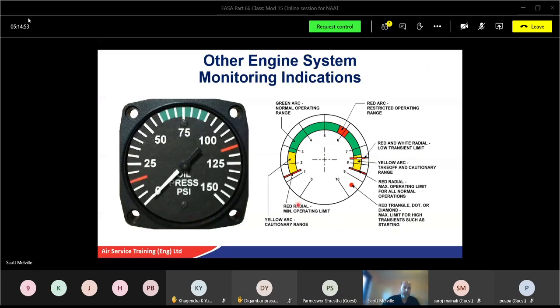Right, I meant to say on the oil pressure switch, we mentioned this in some of the piston engines. You've got a yellow arc range, which is cautionary. Anything in the green range is good, but when it comes to piston engines, remember, piston engines are intermittent, so there's a point of vibration in the engine. It doesn't like to be at a certain RPM. It will vibrate quite a lot. And you'll find that arranged with the oil pressure.